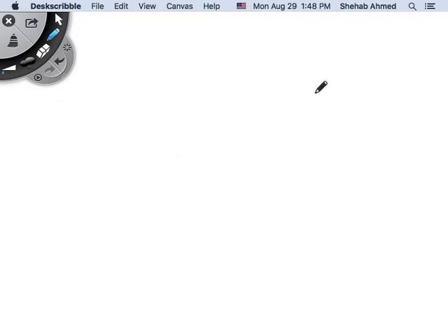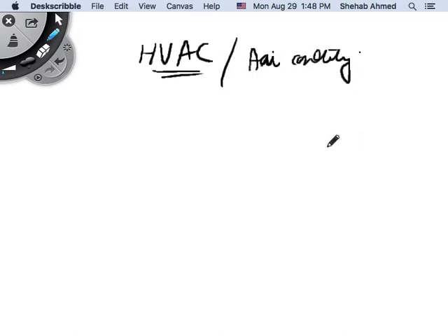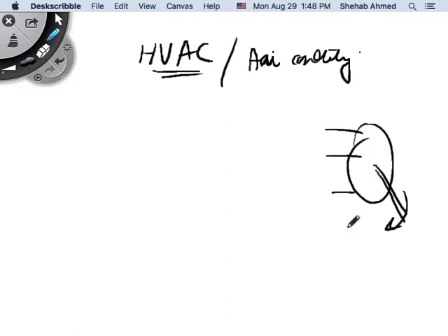How about air conditioning systems, HVAC? Sure. It's typically a compressor that's motor driven. It's either single phase or three phase. Three phase for a building like this, it would be a three-phase motor. For a small unit AC, like the window ACs that you have in your homes, these would be single-phase motors. But in this case, of course, we're running off the three-phase AC grid.